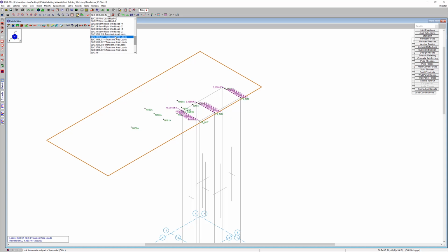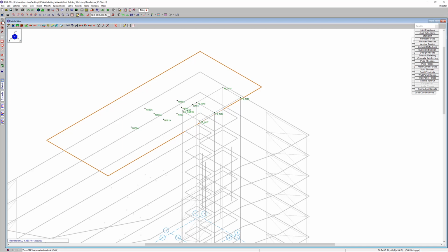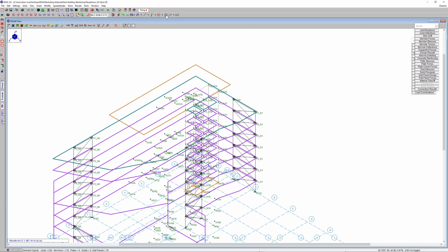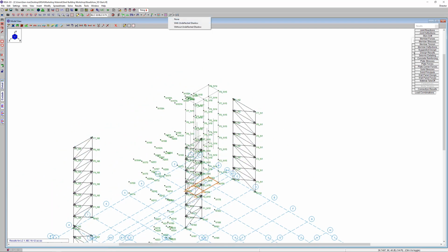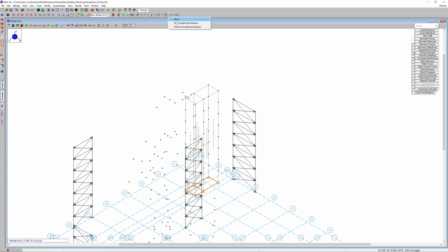This is the distribution taking this point load and breaking it down into the locations of what is going to resist it. So in this case, these line loads at the top of this shear wall here. Now, the first thing that I always like to do, so I'll turn off the loads here and let's get everything back on here. The first thing that I like to do is look at my deflected shape. So let's turn off the nodes here and let's look at our deflected shape.